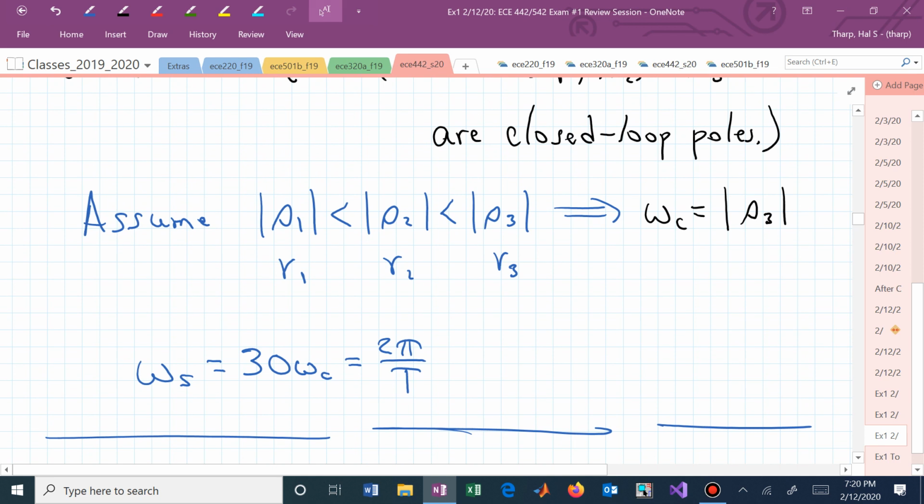So this now is what we would do. We would take the square root of the real part squared plus the imaginary part squared. We just find the hypotenuse of those, and that's what we are going to agree to call the natural frequency of all of those poles, and the one that was the fastest was associated with S sub 3. That's what we use to determine our sampling frequency. We need to base that on the fastest oscillation in the system.